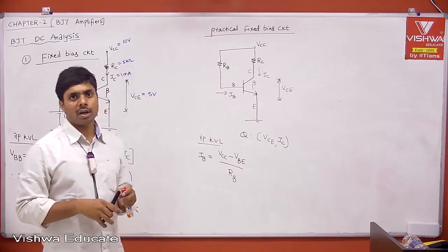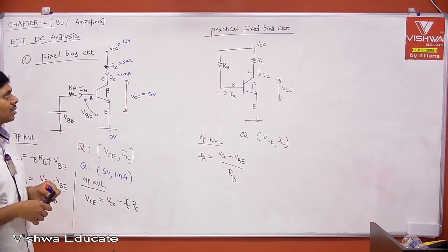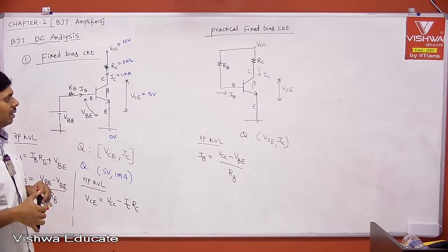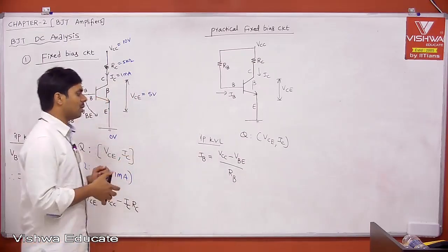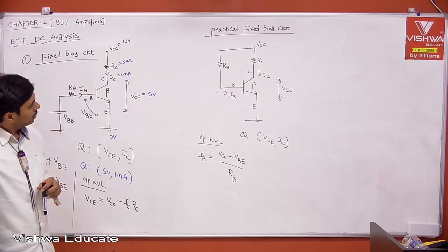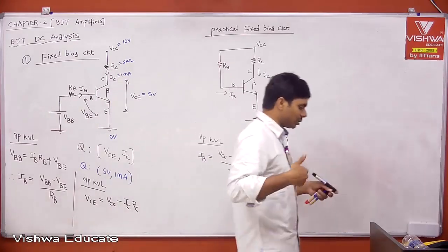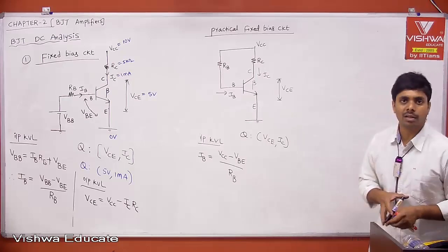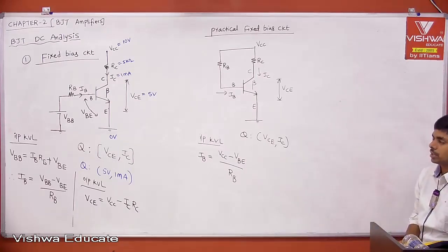Okay. Write down. I don't know, in the last session, if you are able to draw the circuit, fixed bias circuit, which is practical, fine. Else, you take it now and then represent that this is what is your IB. Whatever you want, we can get it. Right? Take it. But it doesn't have any negative feedback. Now we need to incorporate negative feedback such that we can compensate the change in IC due to temperature.